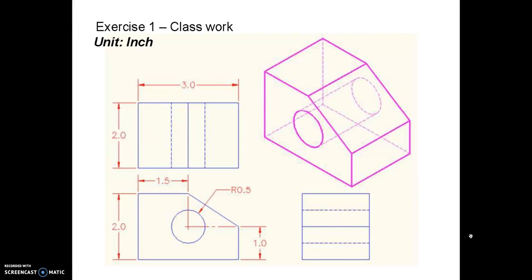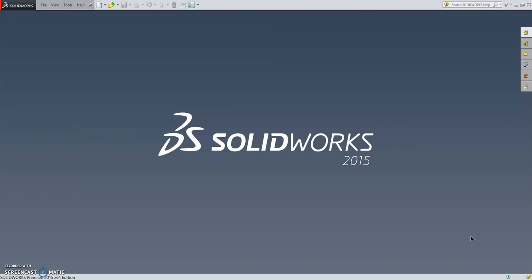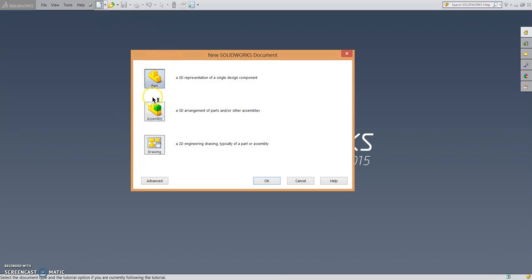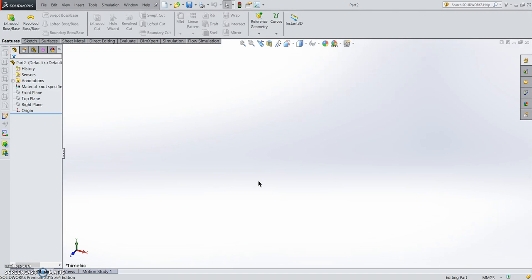So today we are going to use SolidWorks to model something like this. So that's with very simple things. If it's your first time using SolidWorks, then you get a platform, and then all we need to do is create new, and then it will offer us three different file types. Right now we have just started with using a single part. So choose the single part and click OK, and that will be the environment that we are having.